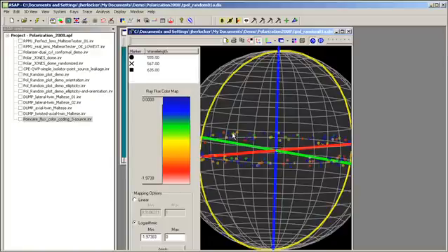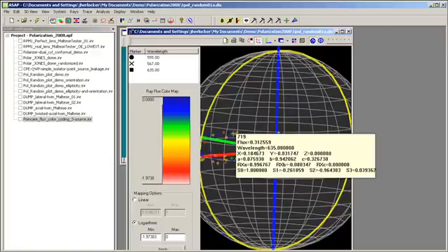And just to give you a little bit more background on what this can give you, let's take a look at one point. We can select a point, and it tells us its index in the distribution file, its flux, its wavelength, its position in position space, its direction cosines, and its polarization data. So we have the polarization reference orientation, and in this case, the Stokes vectors, which are the vectors that are being plotted on the surface of the Poincare sphere.